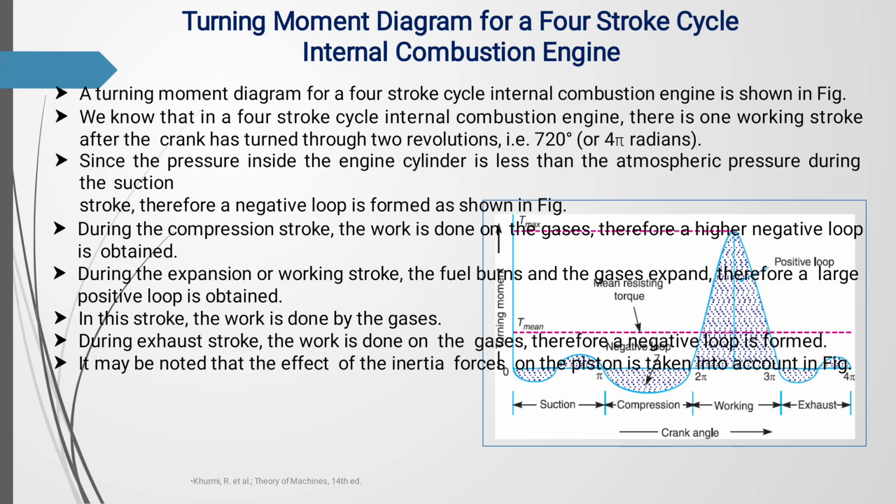So why does this sudden explosion occur? At the end of the compression, the maximum compression is achieved in the cylinder. The fuel particles self-ignite and burn suddenly, all burning within a fraction of a second. Due to that sudden burning, the piston goes from top dead center to bottom dead center.